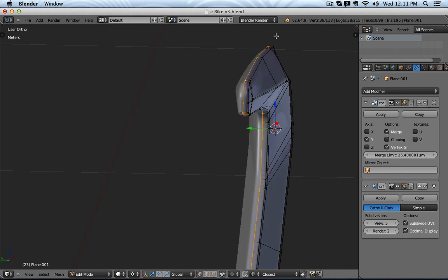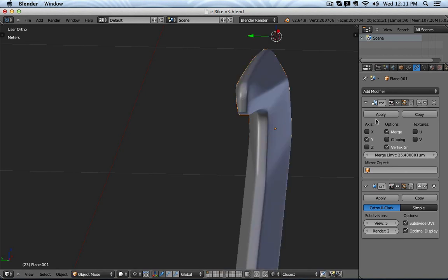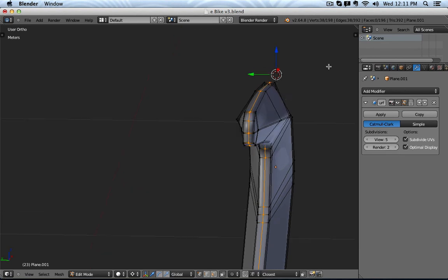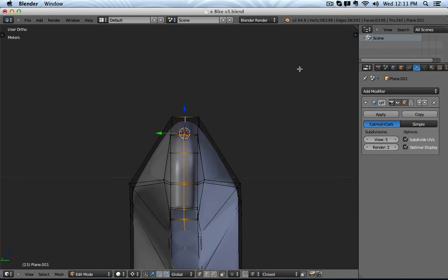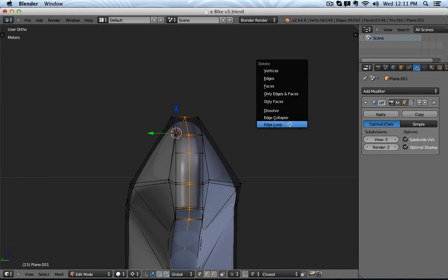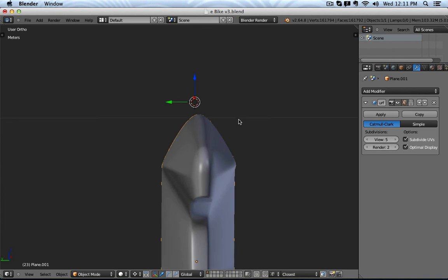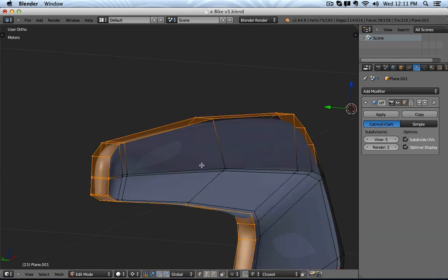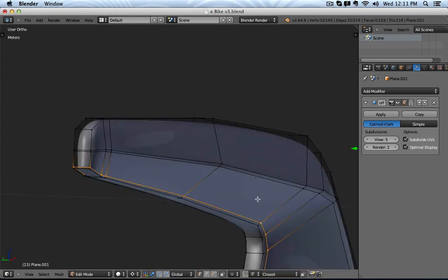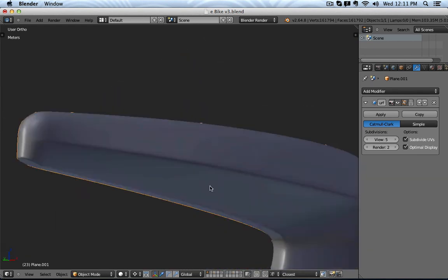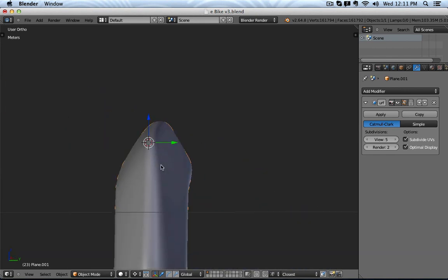So my only way in this type of modeling is I have to apply my mirror modifier, because then I have a solid object, and then I can remove this center line and you will immediately see what will happen. It gets a lot rounder. And then, because I have those loop cuts down here, the inside, for example, is flat, and then the outside is nice and round.